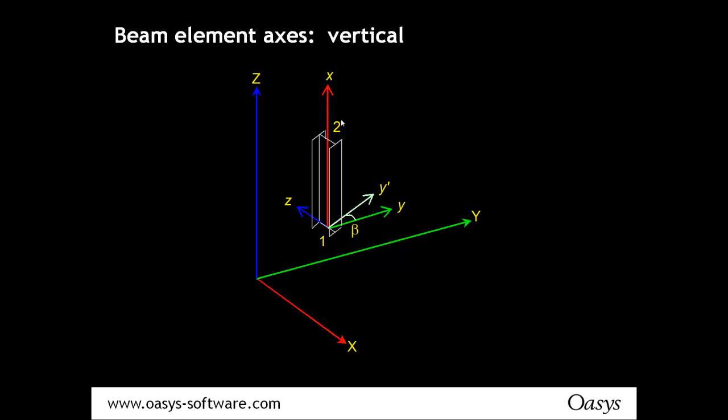If you look at the solids and see your columns spinning around a bit, which can often happen in CAD import, especially if the model is a long way from the origin, then the columns are not quite vertical and need to be straightened up. Of course, the other option is to adjust the verticality tolerance in your preferences, which defaults I think to 2 degrees, but you might want to make that larger if necessary.